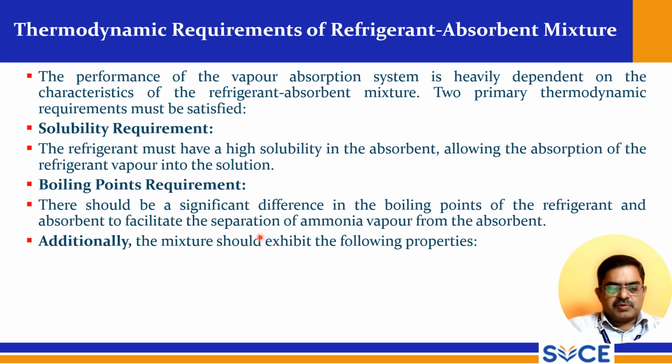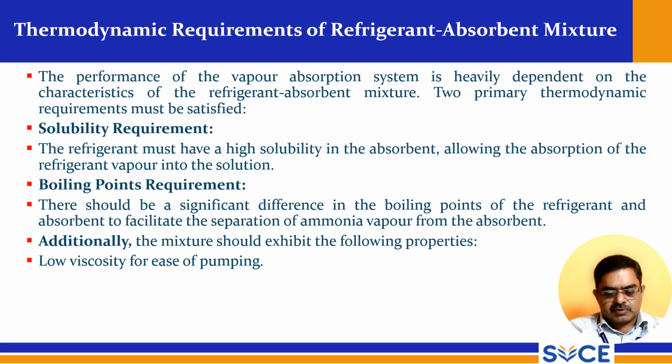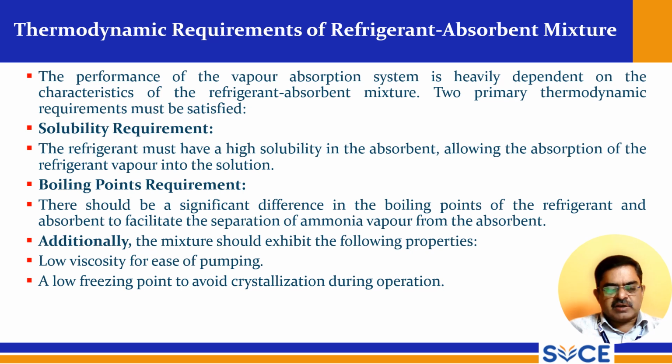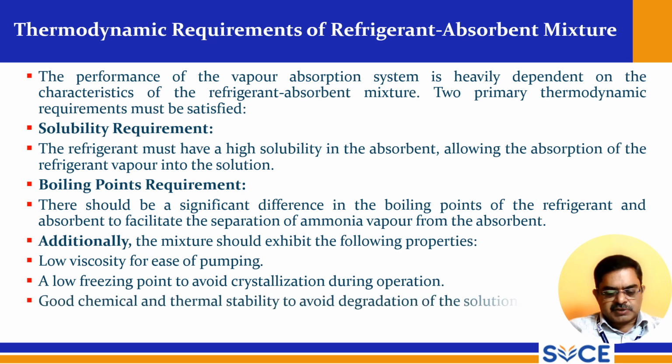Additionally, the mixture should exhibit the following properties. Low viscosity for ease of pumping. So low viscosity is preferred here, and a low freezing point to avoid crystallization during operation. Good chemical and thermal stability to avoid degradation of the solution, and no significant irreversible chemical reactions are required. So there should not be any irreversible chemical reactions.